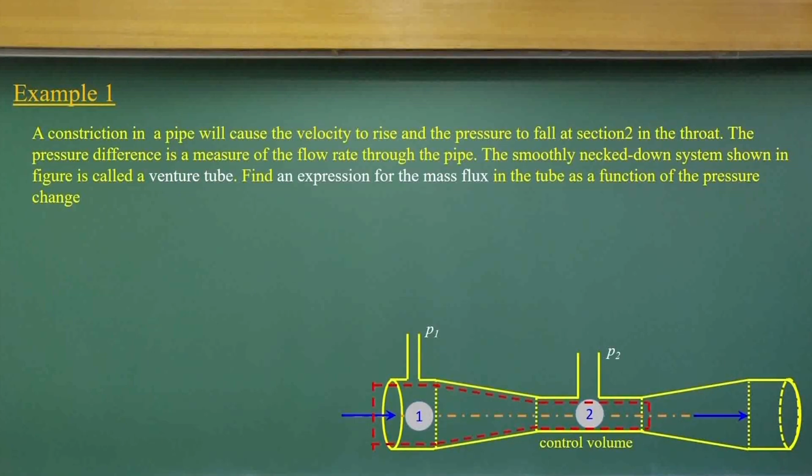But I always encourage you to sketch the control volumes as well as draw streamlines. After drawing the streamlines, apply Bernoulli's equation between two points. That part should be looked at, and always highlight what the assumptions behind it are. What are the assumptions you have made? That should be highlighted before solving any fluid flow problem.